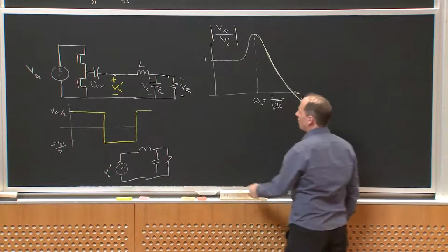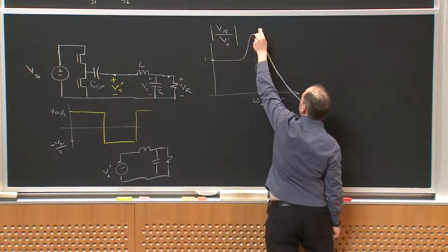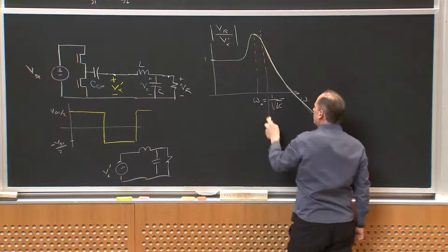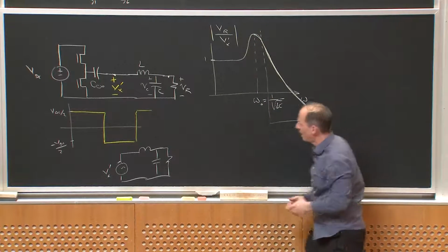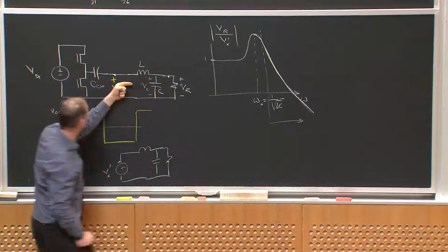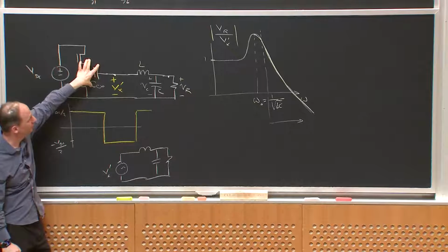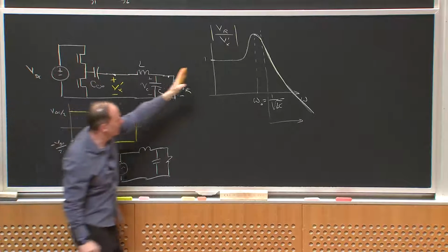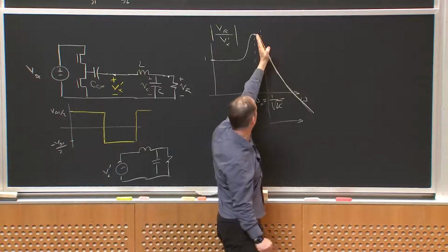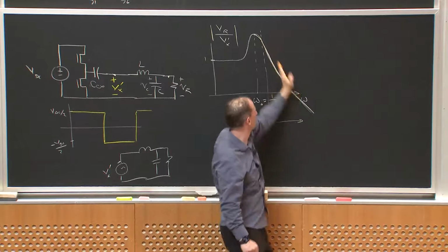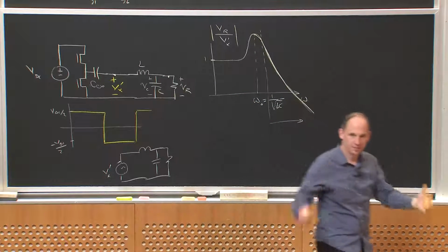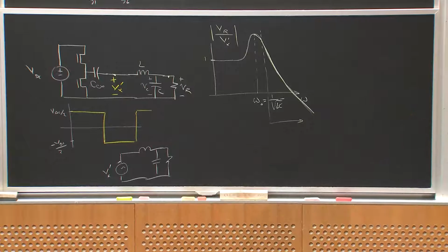And again, if I'm operating up here in this regime, I'm going to have an inductive input impedance coming in. So again, I can soft switch these devices, zero voltage switch these devices, okay? And now I can, again, by controlling the frequency of the drive, control the amplitude across my resistor and hence control power. Any questions about that?